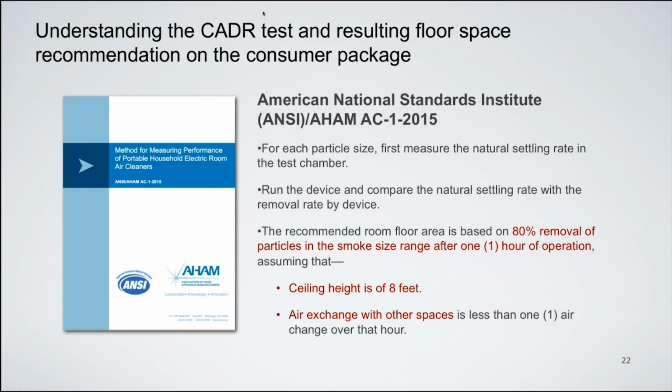So those are two important assumptions, and they can affect your selection or the wisdom of your selection. If you have more than 8-foot ceilings, you probably want a bigger one. If you have an especially leaky building, you probably want a larger air filter, one that's designed for more square feet. That would be the case, for instance, if you have very leaky windows, older windows in an older building, or if you crack the windows from time to time and you're living next to a highway, then you probably want a much bigger air cleaner. And one can't expect to clean the air if the windows are open all the time.